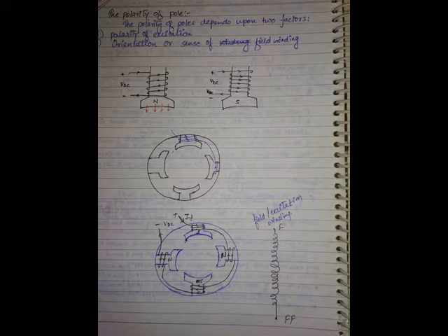So you collect the mechanical output again from the armature. So the rotating part is the main heart of the DC machine, whether it is acting as a generator or a motor. You give mechanical input and collect electrical output, or give electrical input and collect mechanical output, entirely through the armature. Keep the heading: armature.